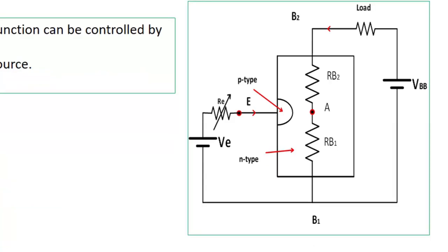Now in this circuit, two resistances are inserted. In series with VBB, a load resistance is connected. This is because if our transistor is on and its internal resistance reduces, then nothing would oppose the current flowing from VBB. VBB would then be short circuited and a high amount of current would flow, damaging the DC source VBB. Across the emitter terminal, a resistance is connected to control the emitter voltage applied across the UJT.